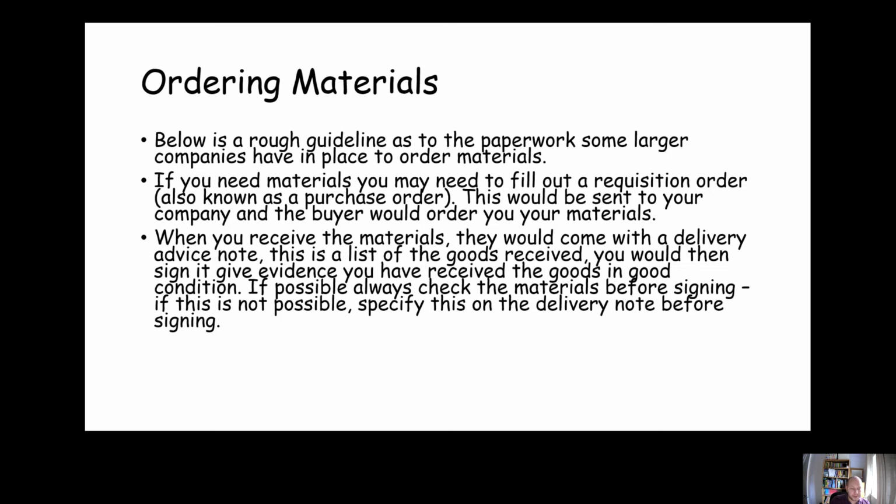Worth noting, it's not going to come up in the test, but quite often when you're taking all the materials off the van on site, you don't have time to check them all before the delivery driver goes. So if it was me, what I always used to do is I'd write "unchecked" on it before I signed it, and that way there's a bit of comeback if all of the stuff that they've said they've delivered hasn't been delivered, which does happen, you know.